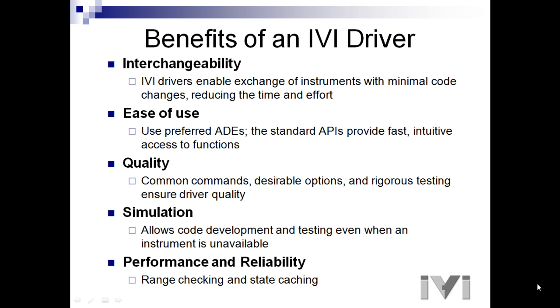Number one is interchangeability. IVI drivers enable the exchange of instruments in your system with minimal code changes, reducing time and effort. Two, ease of use. You can use your favorite ADE such as Visual Basic, Visual C++, LabVIEW, LabWindows, MATLAB, or VEE. The standard APIs provide fast, intuitive access to functions. Three is quality. You'll have common commands and desirable options. The Foundation's rigorous testing ensures driver quality.